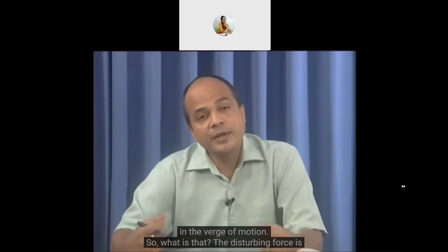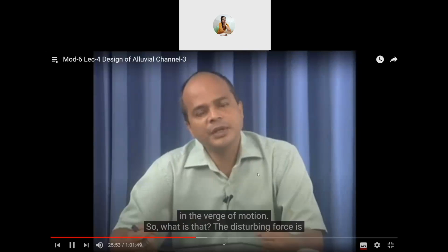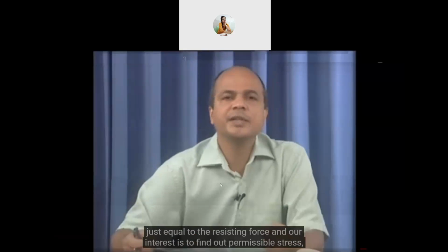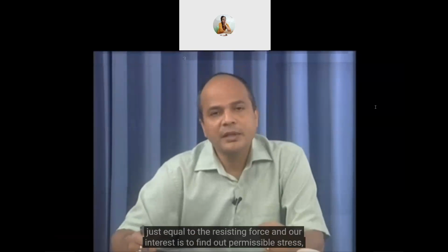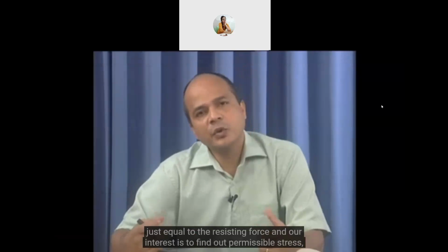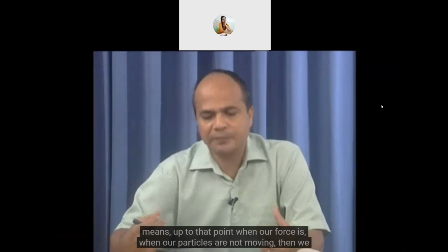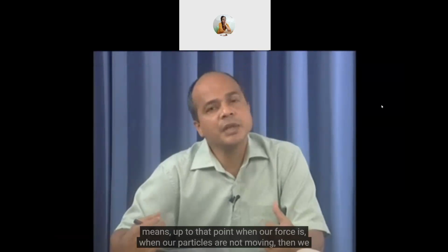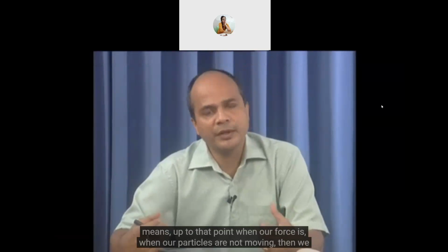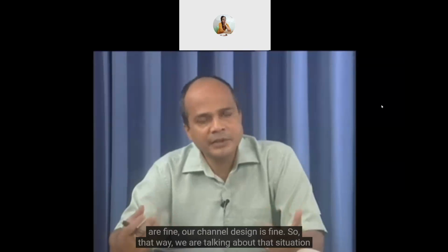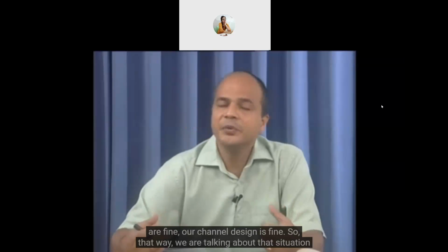So what is that? The disturbing force is just equal to the resisting force. And our interest is to find out the permissible stress, meaning up to that point, when our particles are not moving, we are fine. Our channel design is fine. So we are talking about that situation.